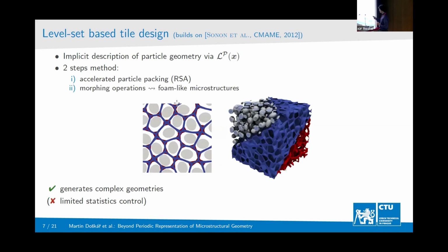But also you can take linear combinations of the nearest neighbors, second nearest neighbors, and third nearest neighbors functions to go from standard particle packing to something that looks like a Voronoi tessellation, this blue one. But this one is more, let's say, complex. It's not a standard Voronoi tessellation. It's even more complex. And there is a variant called Laguerre tessellation, which adds weights to the seed points in Voronoi tessellation. But this approach adds some local metrics to the seeds. So it's even more complex, and it gives you more freedom in designing the geometry.